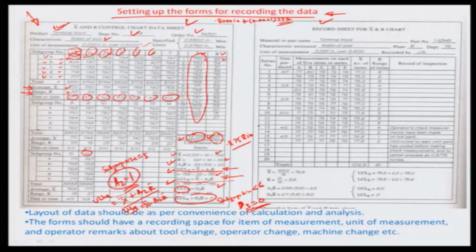And so, above 6 there is always a lower control limit for the range which comes into the picture, and these are simply statistical observations which have been recorded as a chart out of many such control charts to see if the process is in control or out of control. And then the D4 value is recorded as 2.11 in the Shewhart control chart, corresponding to a subgroup size of 5. So this D4 is recorded as 2.11, and so you can have an upper control limit for the range, and the lower control limit for the range in this case, because the subgroup is less than 6, is equal to 0. So, this is the whole control logic behind plotting the control chart.